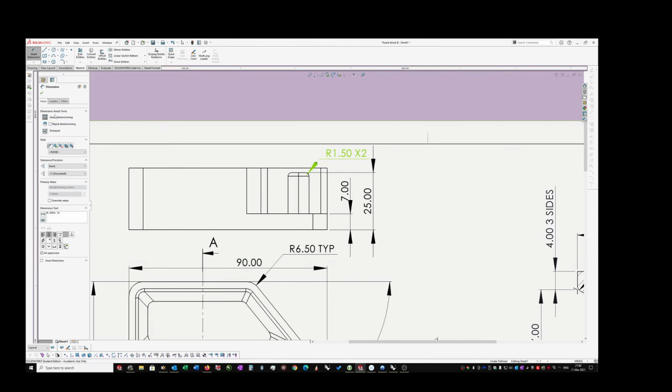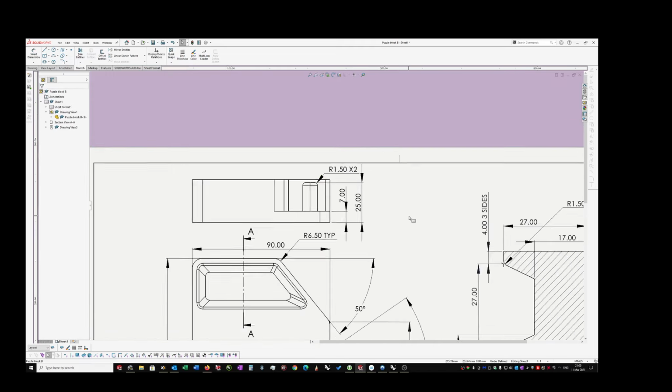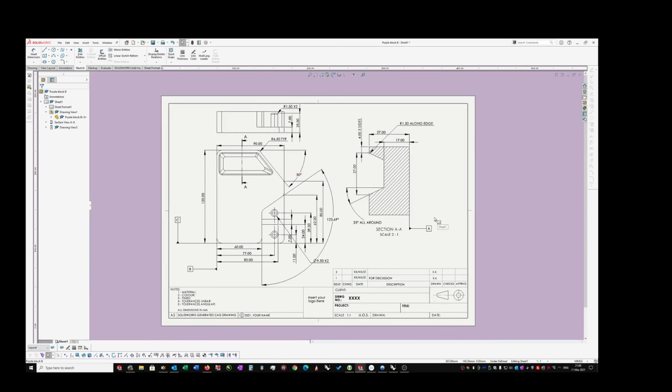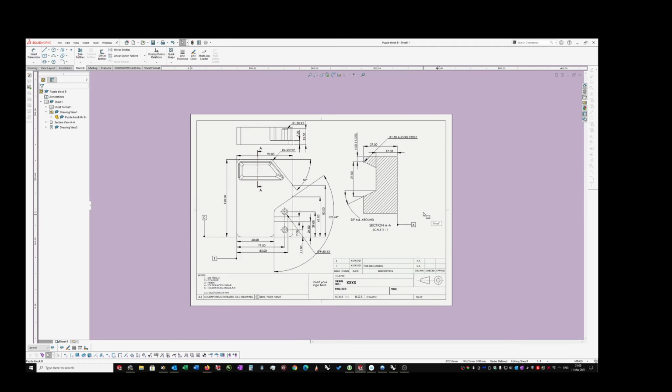Okay, once again, this program is playing with my settings. Right. And that's it. I think you're done. I don't see anything that's missing. All of your position dimensions are in place. All of your size dimensions are in place. The angle dimensions are size dimensions. This shape follows that outside shape, and so that 50 degrees will also be repeated here. That angle is repeated on all 4 sides. That radius goes on around all of those. We've got the heights in, and we're done.